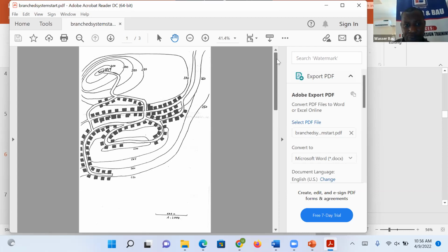This is where people have problems. There are about 25 houses connected to this node. All you need to do is to determine the demand for one house and multiply by 25. That becomes the demand at this node. So if the water board comes tomorrow to take measurement, all you need to know is the consumption of everybody along this line. You will just open this place and take reading.